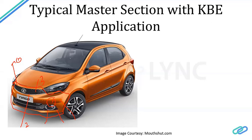This is a fog lamp ring, which is a different part. This is another part. So there are so many parts. There is one bracket coming over here, which is not visible, which interfaces with the fender and the bumper. So there is an interface between the headlamp here and the bumper. So there will be some sections which you need to consider.